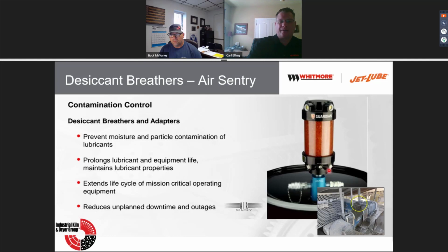It's got valves on the bottom and exhaust ports. It's got 4 of them up here for the intake. So the air will come in here and go through the desiccant. You've got a stainless steel mesh here that will handle the particulates as far as physical. The air will go through here, and the moisture will be taken out of it, going into either the drum, hydraulic reservoir, or gearbox.